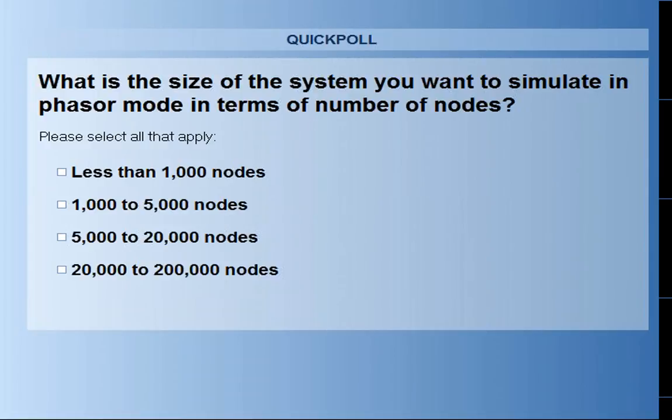In this slide, I show you a simplified version of the Hydro-Quebec power grid being simulated in ePHASORSIM. What you see in this slide is a panel that was constructed in test drive, which allows us to trigger events into the simulation and visualize those events in a separate panel in test drive, or, as we will show later in the demo, we can actually communicate all of this action and those simulated signals through standard communication protocols to the RTDMS product of the Electric Power Group company.